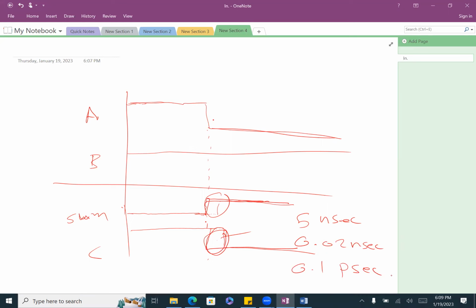We should use a term, and this term will represent the delay. And in digital design, we use something called delta. So when we talk about delay, we talk about how much delta the gate will delay. So you don't have to worry now about what technology we have now, if it's slow or fast. You just represent it by delta. So we say, this gate is going to take delta time, delay or speed to do the operation or to translate to the next stage, right?